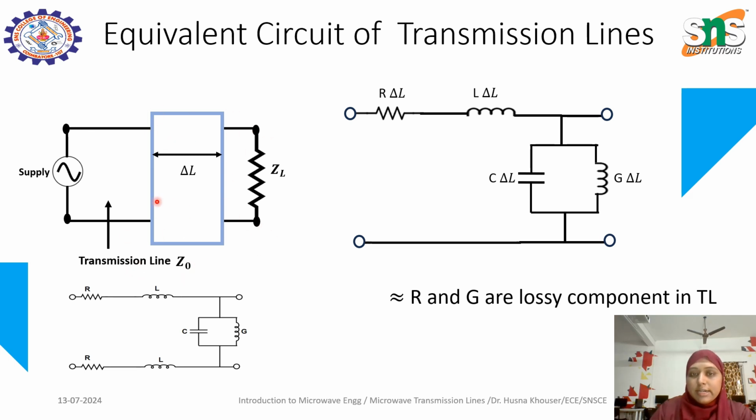For calculating the characteristics of the transmission line model, you can see I have used only the top line, because when we find the characteristic impedance of this particular wire over a particular distance, we have to measure the signal with respect to the ground plane. If we go for ground plane analysis, it is not required to mention the R and L components, so that's why we have mentioned a plain line component.